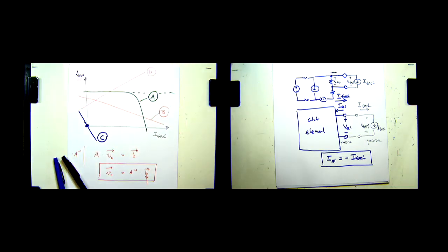You think that's possible? Well, I'll tell you. You can create this, but you need negative resistors. With the sign conventions that we've used here, to create this, you would need negative resistors. Of course, if we define the signs differently, then suddenly the curve looks different. So just be very, very careful about signs. There is nothing wrong here.